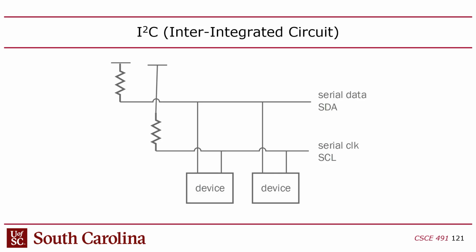All right, so I only have a minute left, so I'm just going to introduce how all this fits in. The reason I talked about all this was because the next bus technology we're going to talk about is I2C. I2C is a fancy way to say IIC, and IIC is an acronym that stands for Inter-Integrated Circuit. This protocol is standardized. So unlike SPI that was very informally defined, where you could hack it and change it, and the transaction protocol was arbitrary, with I2C that is not the case. I2C is very strict about how you use it.